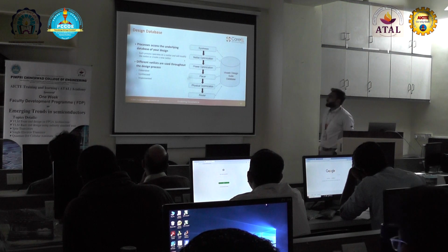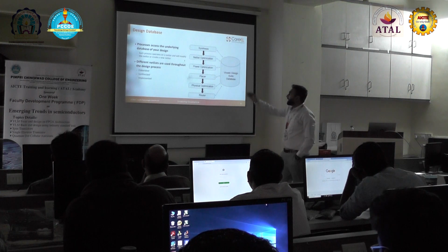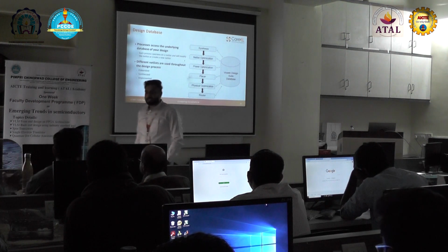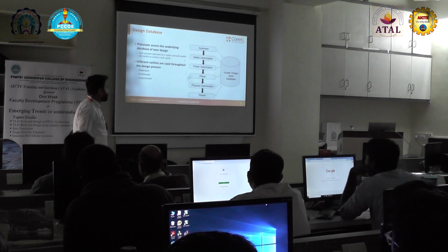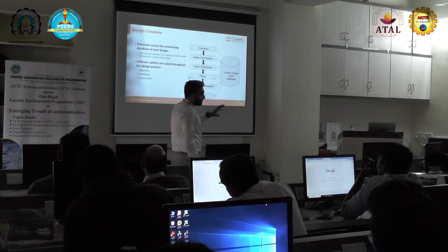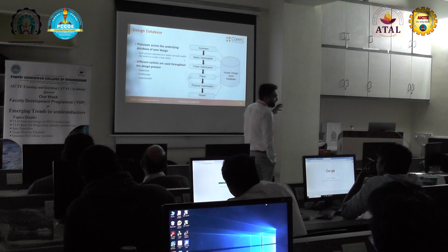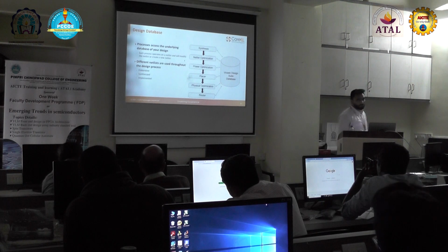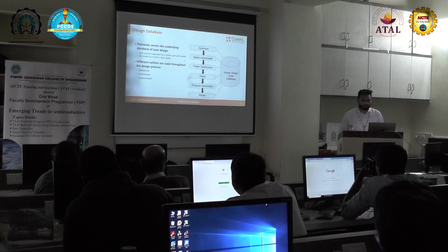So, once the synthesis has been done, we will get the netlist optimization. Once the netlist optimization is done, it will do the power optimization. Once the power optimization is done, it will go to the placement. After placement, it will do physical optimization. After physical optimization comes routing. Routing is the last step.